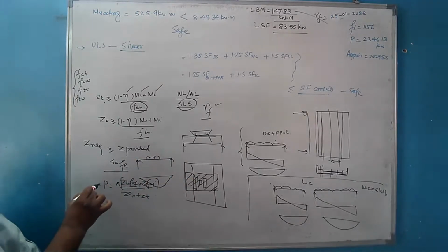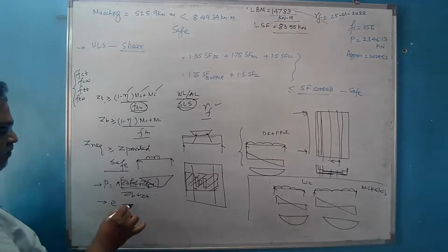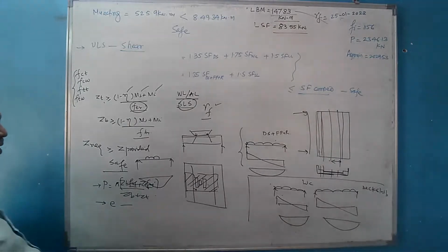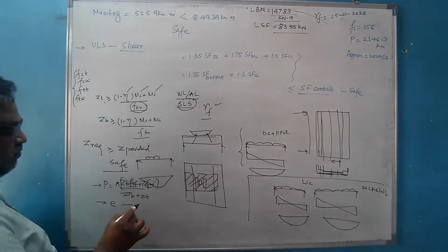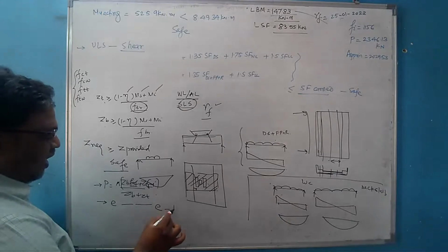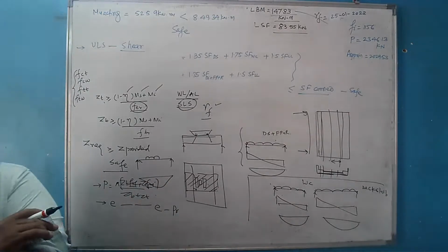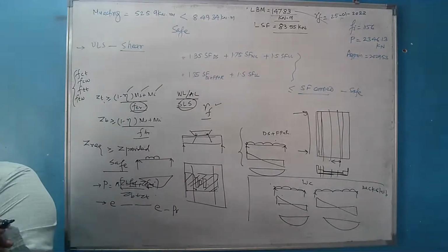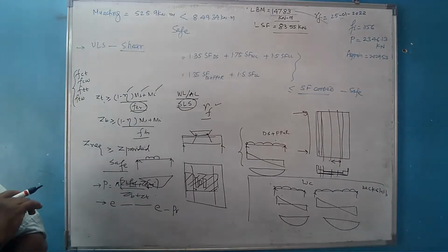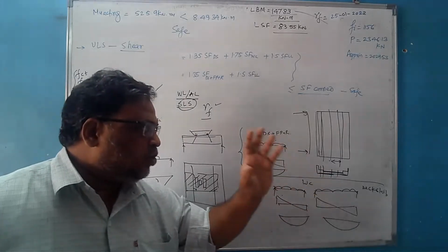Then we had determined the magnitude of pre-stressing force. Then we had determined the corresponding eccentricity from the respective equation. But it was found that the eccentricity was going outside of the section. Then the eccentricity was restricted, and the revised value of pre-stressing force was calculated. After this, we had located the safe cable zone where the cable is to be provided.